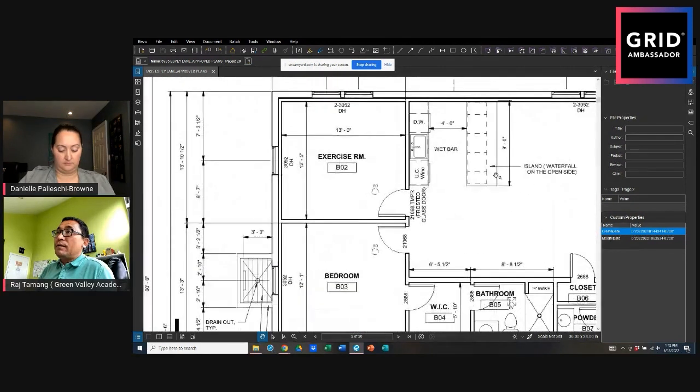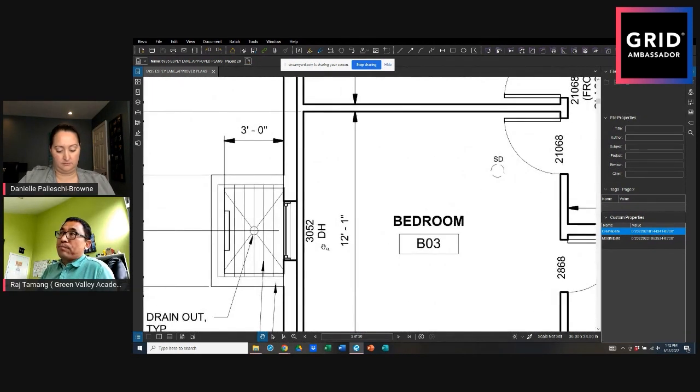And also the window, let me go back to the window here. This window could be on a first floor or second floor. So the regular window is a glass but not tempered. But if the window sill is less than 18 inches, then the glass has to be tempered. That's part of the requirement. And you're thinking, hey, why don't we do tempered everywhere? Yeah, you can, but the cost is double. It's not cheap. Tempered glass is almost double the cost.